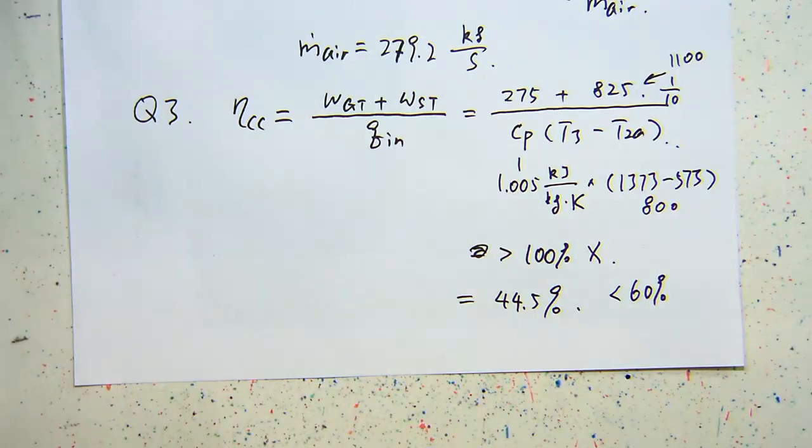We already consider ideal cycle in most cases. There is no heat loss in the combustor. There is no heat loss during this heat exchange process. So heat loss has already been minimized in our problem, and also the efficiency is 85% for the compressor and 90% for the steam turbine and gas turbine.